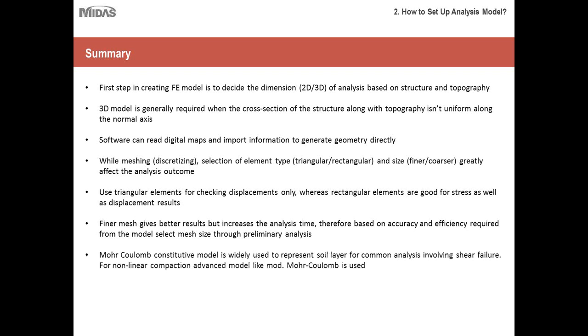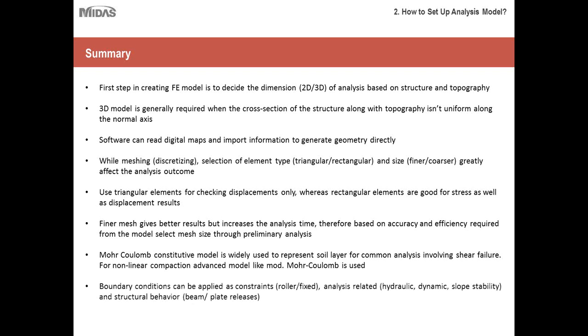Then Mohr-Coulomb constitutive model is widely used to represent soil layer for common analysis involving shear failure. But for nonlinear compaction, advanced models like modified Mohr-Coulomb should be used. And the boundary conditions can be applied as constraints such as roller or fixed, analysis related such as hydraulic, dynamic, slope stability, and structural behavior related such as beam or plate end releases.